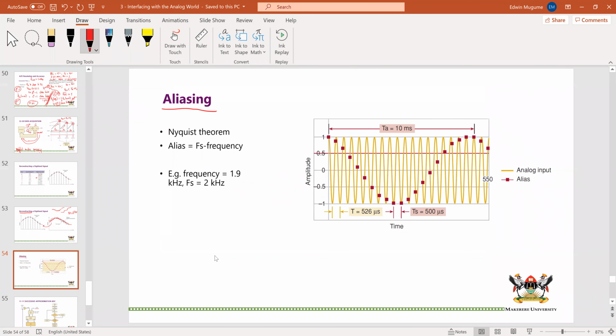So if my maximum frequency, Fmax, is 10 kilohertz, then my sampling frequency should be greater than or equal to 20 kilosamples per second. Sometimes you could confuse that with kilosymbols per second, which we know works within QAM, QPSK, and so on. But in this context, it means kilosamples per second.